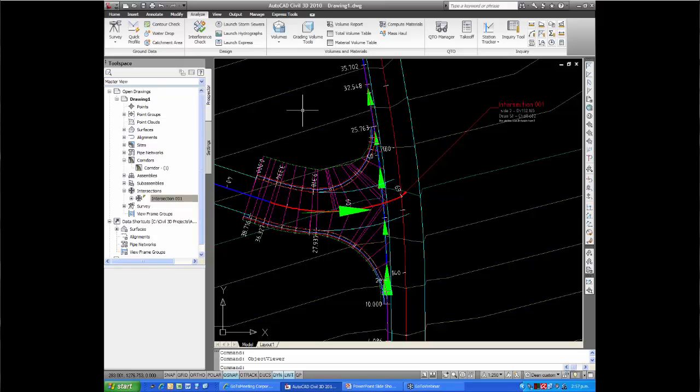In fact, we can do things like work out the length of the top of curb, so you can say the linear length of the curbing that is required in this corridor, which is also useful. So I'm just using the quantity takeoff bits and pieces.